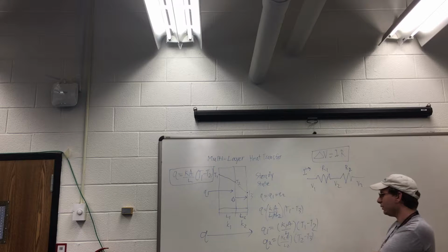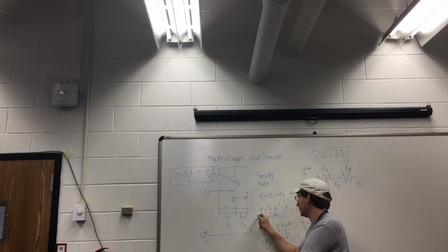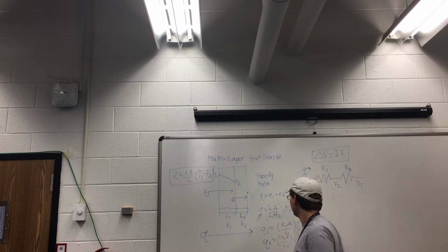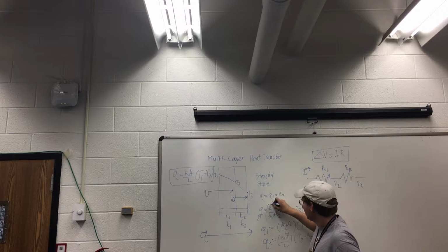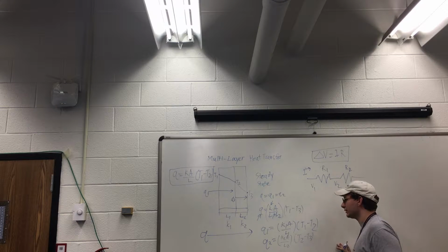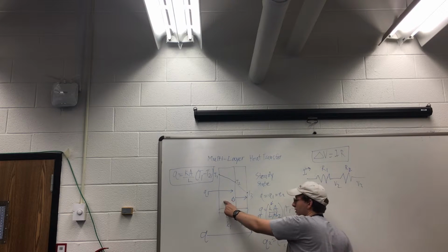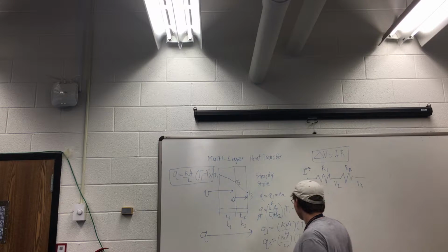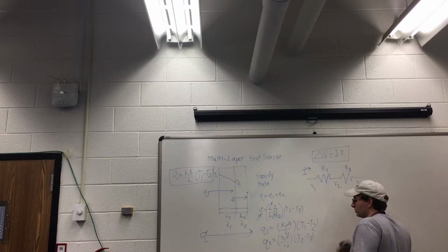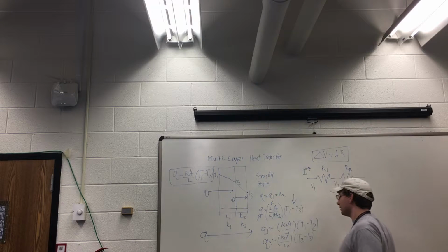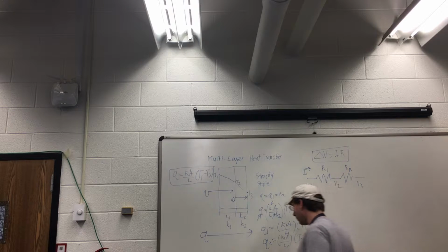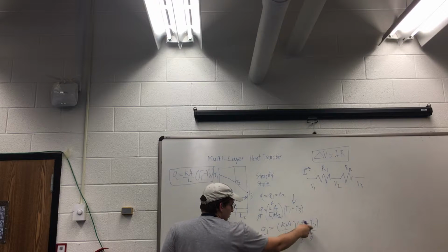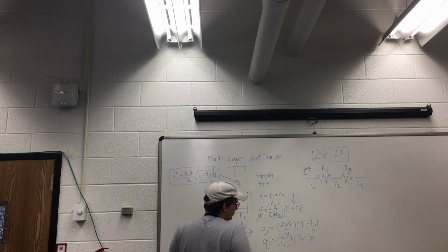So we want to find what Q is equal to. Now, we can't just use this equation I've written because we don't know what that K is, because it's not this material's property and it's not this material's property, it's somewhere in between. So what we're going to do is try to find something that gives us this temperature drop, and we'll just call it a day. So we're just going to solve for these temperature differences and then add the two of them together.